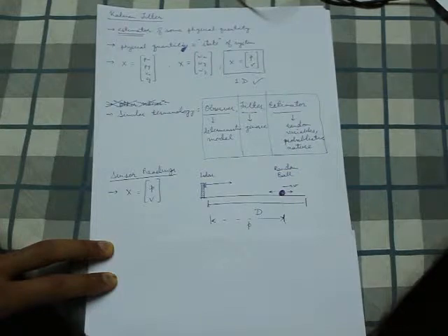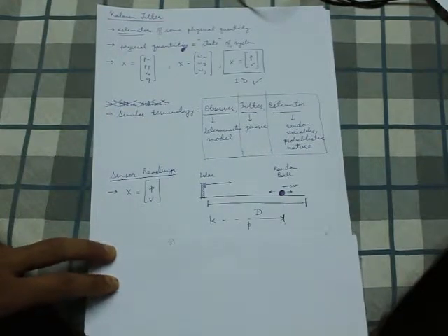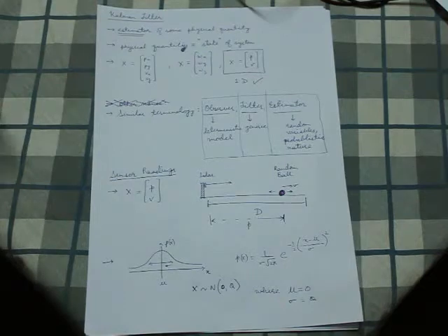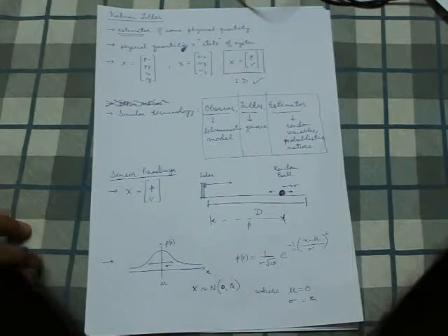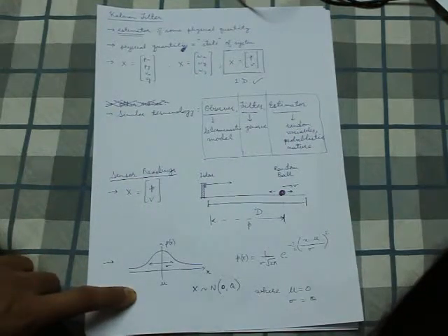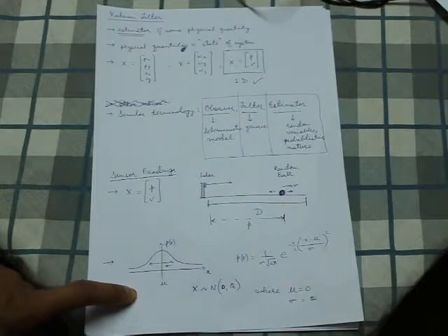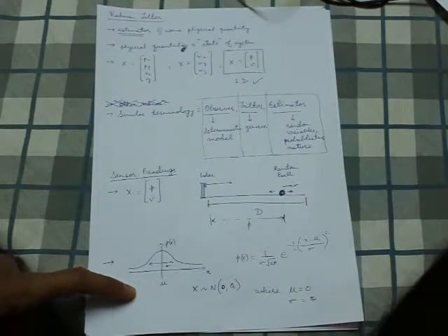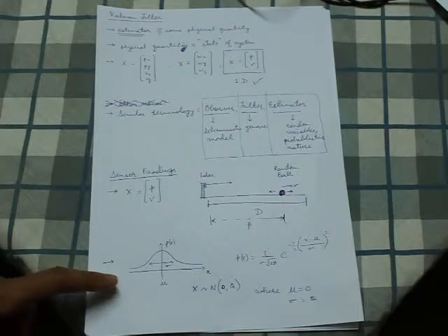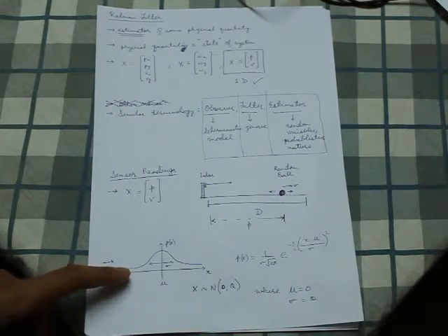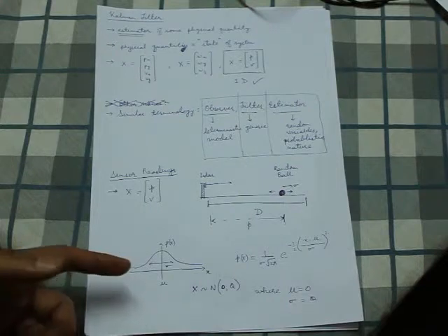Now generally the manufacturer of the sensor also provides some uncertainty within which the sensor works, and this basically means that the readings that the sensor provides are not always certain, and they give a probability distribution to denote this likeliness of the reading being correct. So if the LiDAR sensor were to give a value, say 5, then they will say the value 5 is likely to be the case with a probability distribution of something.